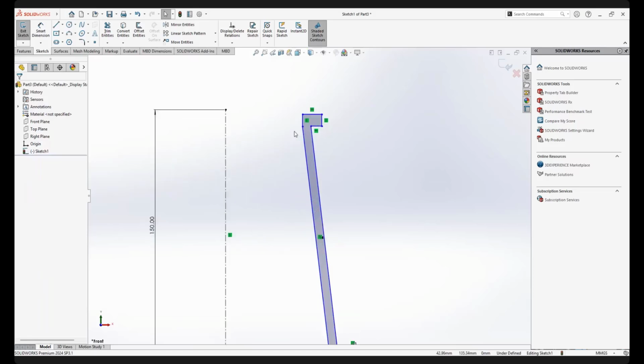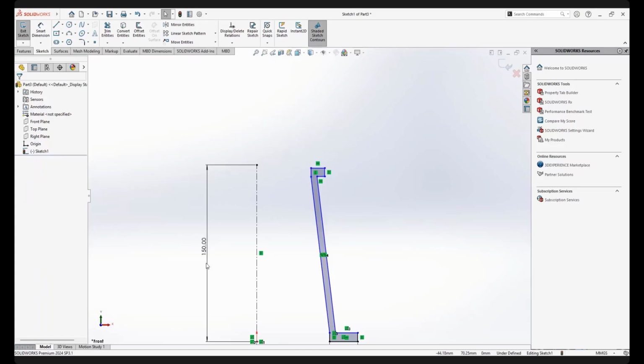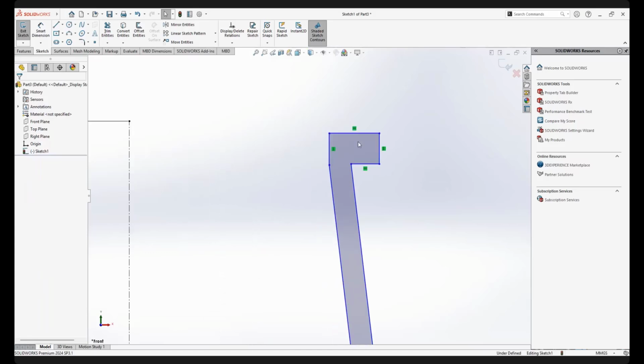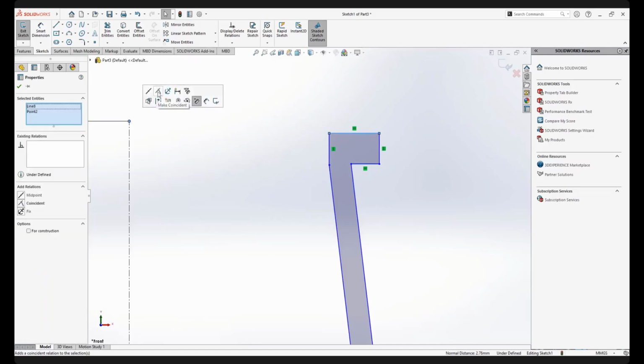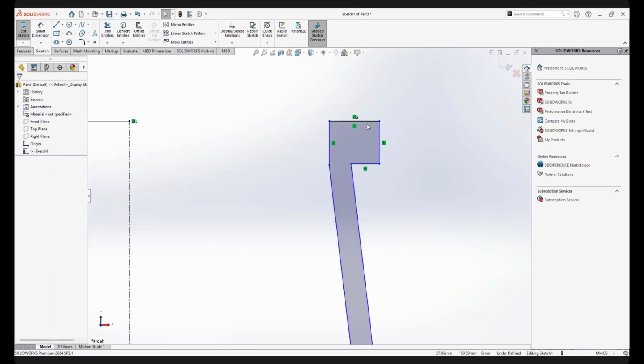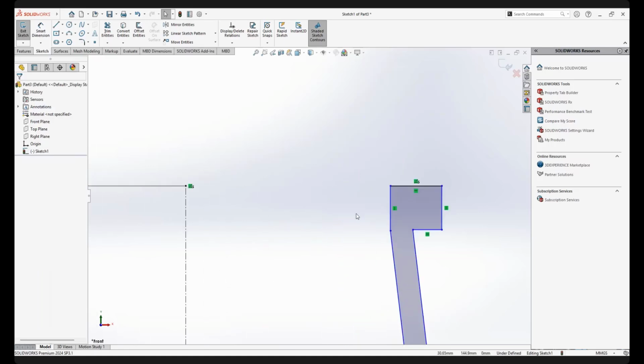All right, another thing I have not set yet. What is this one to this dot? We have not set, define the total height is 150. What is the relation of this line to this dot? Line and dot will be coincident. You are right. Can you see it become black? I cannot drag, because we have set the relation to this point, 150, right? Okay, already done.